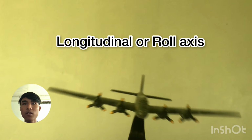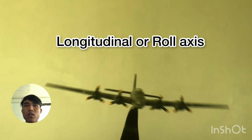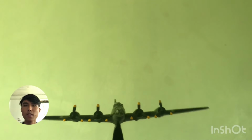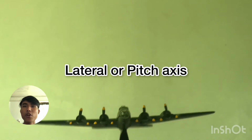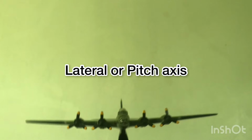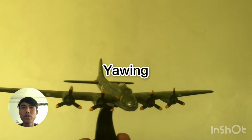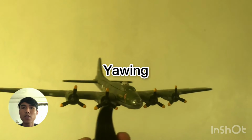The longitudinal or roll axis extends through the aircraft from nose to tail, passing through the CG. The lateral or pitch axis extends across the aircraft on a line through the wing tips, again passing through the CG. The vertical or yaw axis passes through the aircraft vertically, intersecting the CG. CG is the center of gravity.